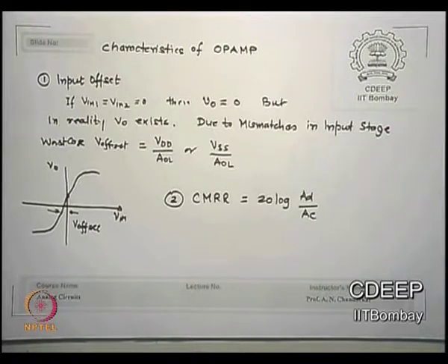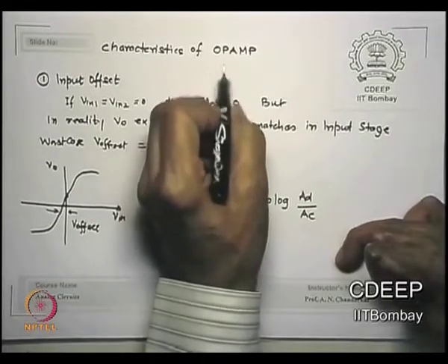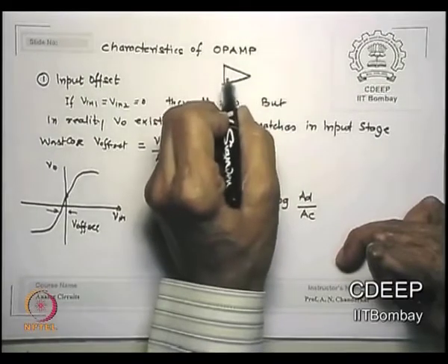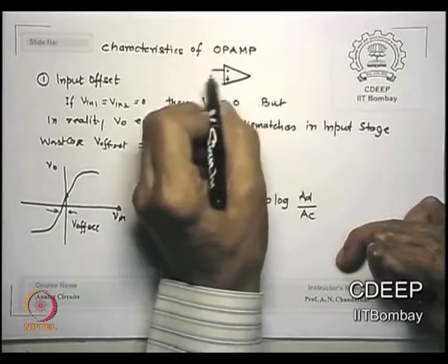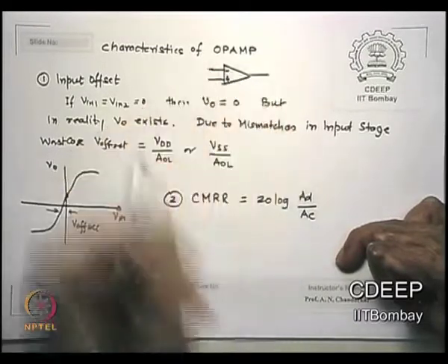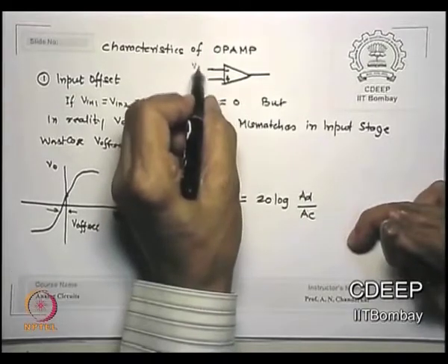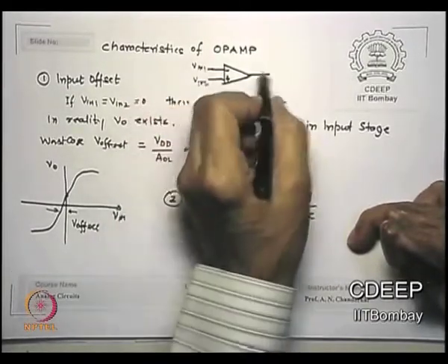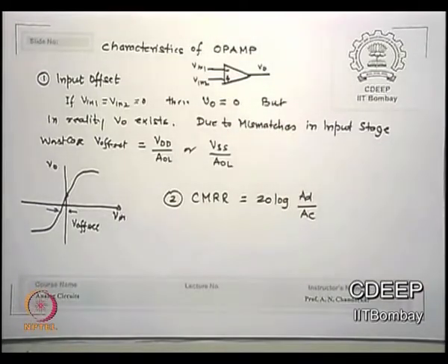is the input offset voltage, okay. Now what is the term we are talking? So if you have an op-amp, which is symbolized something like this, plus minus, Vin1, Vin2 are given names, and this is V0. We say in the first stage, if both inputs are 0, output should be 0 because no current. Is that clear?